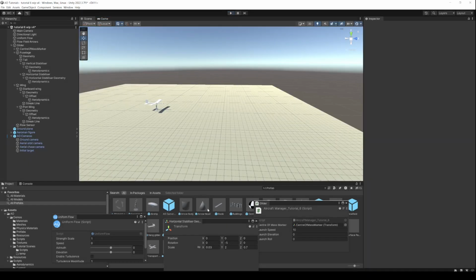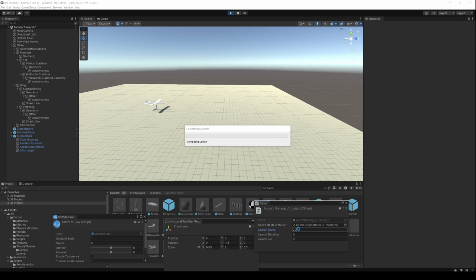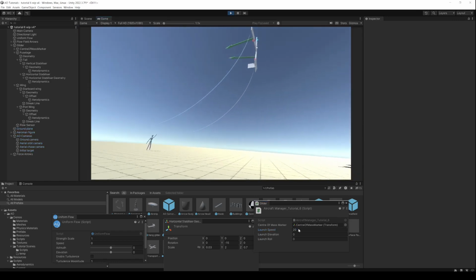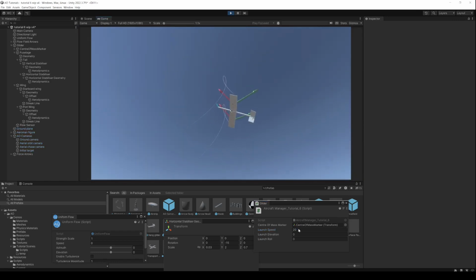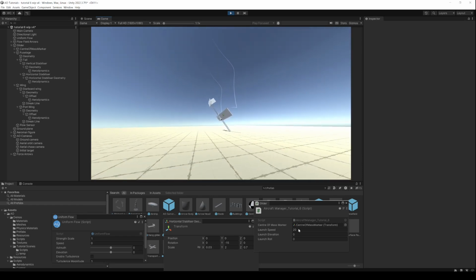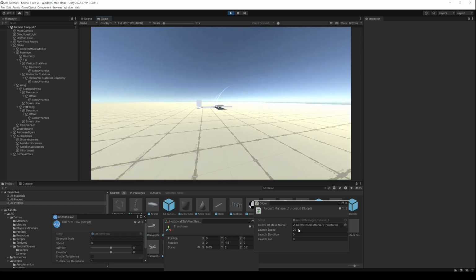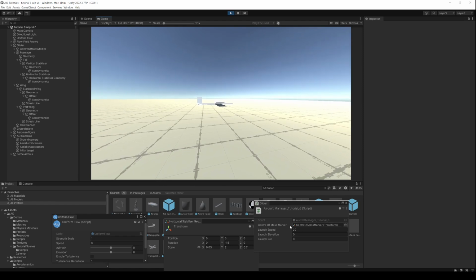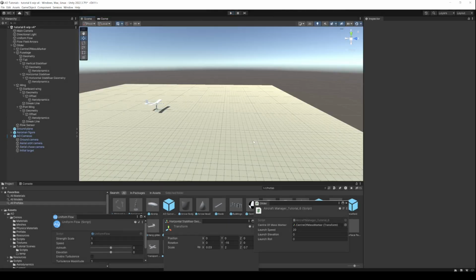Okay, let's do some flight testing. Well, this is simulation, so we can do whatever we like. When we had it set to -15 on the horizontal stabilizer, it climbed and then it stalled. But what happens if we did that but just chucked it a bit harder? So now I'm going to throw it at 20 meters a second. See what happens. Okay, that was pretty exciting. So it did a stall and then kind of did a flip over and hit the ground. But that's pretty cool. So it looks like we just need to chuck it a bit harder.